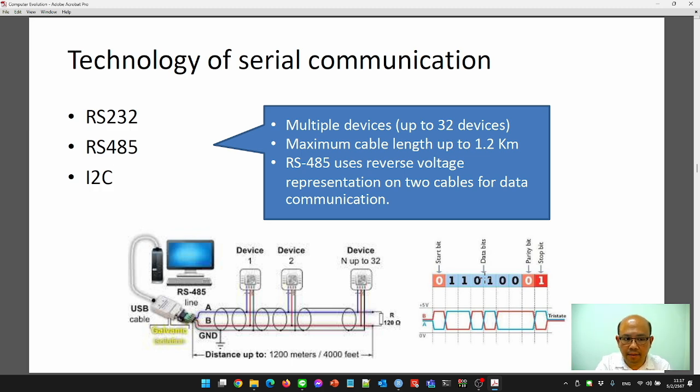It uses only 2 cables, like RS232, but differs in the protocol interface. Inside, it is a bit and its reversed bit. Looking at these pictures, bit A is negative and bit B is positive. It is a differential pair, like the crosstalk we looked at in the last slide that I showed you. This is made for long distance to protect against noise signals.